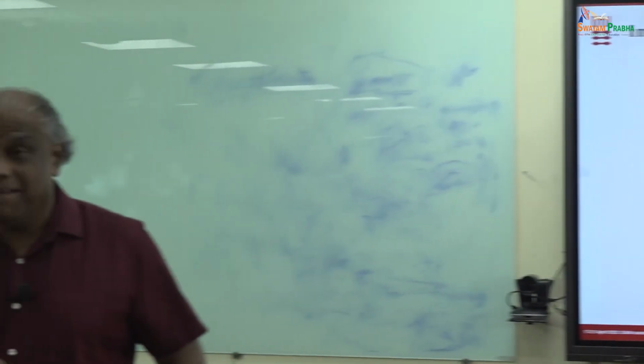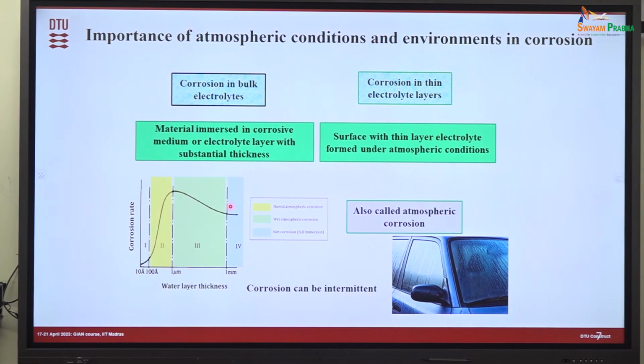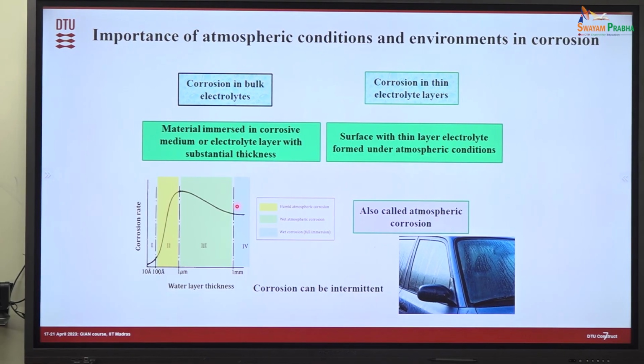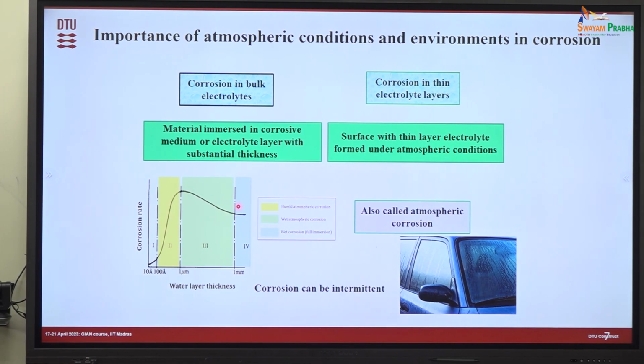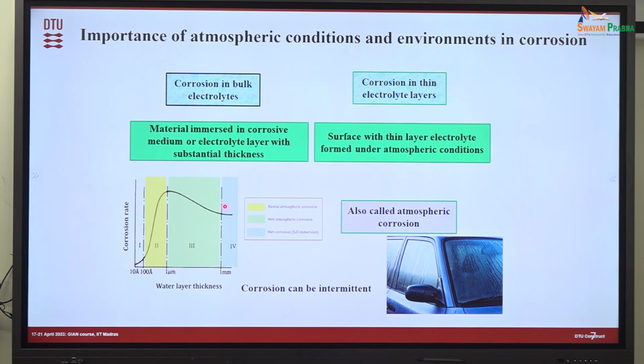Yeah, leak current is there, but again, if I do the water film thickness, usually we will not get a behavior like that. That's because we discussed having a higher voltage on the PCB and water film thickness. No, you think about the cathode reaction. We don't have oxygen as a cathode reaction because you have enough voltage for water splitting. So oxygen limitation is not there in that case.